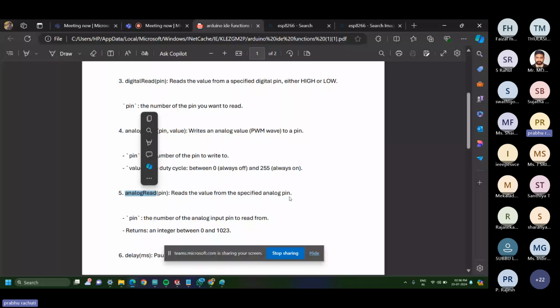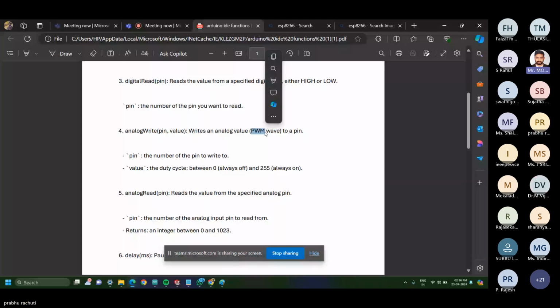And analog write is nothing but a PWM value. It is used with a motor driver which will control the motors. We'll complete one task on each of these functions and sections. Here analog write will be used for controlling a motor driver. A motor driver controls the speed and direction of the motor, or any other servo motor, stepper motor, normal DC motor, or BLDC motor.